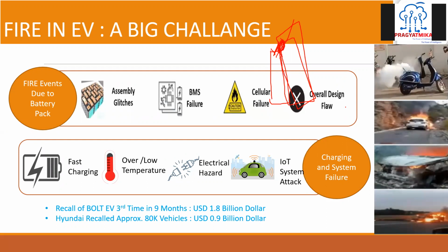So it is a design flaw. If the fire is due to the battery pack, such kind of issue is there from the inside of the pack. Thereafter, there are user behavior issues like fast charging. Even if the battery pack is not supporting fast charging, we are doing fast charging of it. It is at the cost of safety, because it will definitely increase the temperature if there is no active thermal cooling system inside our pack. Going under over or low temperature conditions can also lead to the failure of our pack. Then there are electrical hazard conditions, like connectors are not good.